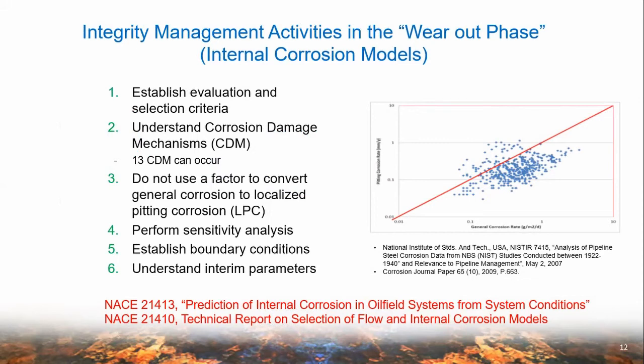To begin with, start using two NACE standard technical reports to understand and select models. Technical report 21413 provides evaluation criteria using 13 different criteria. It also compares 17 commercial models. 21410 provides 6 steps to select an appropriate model.